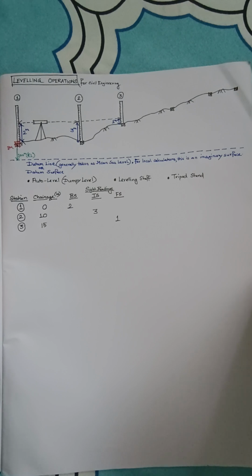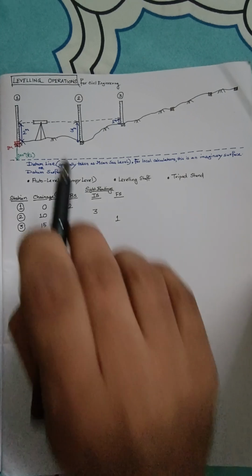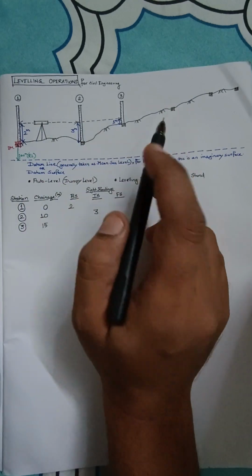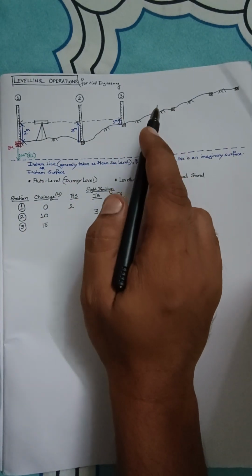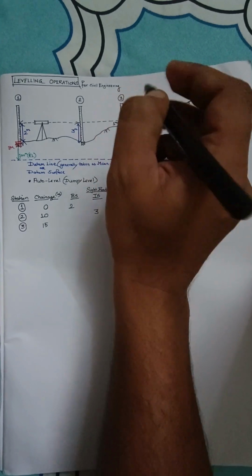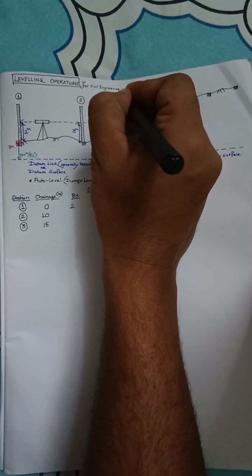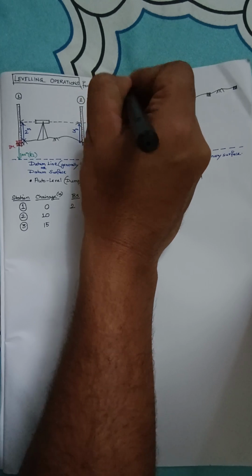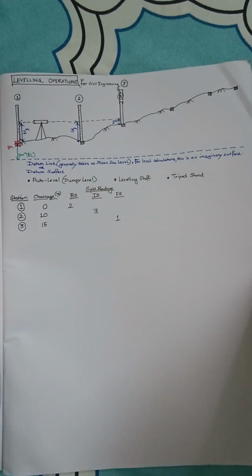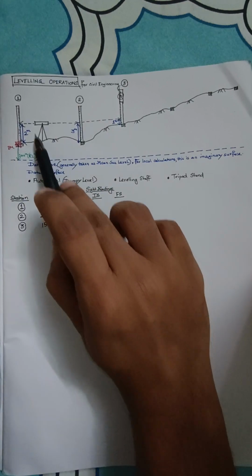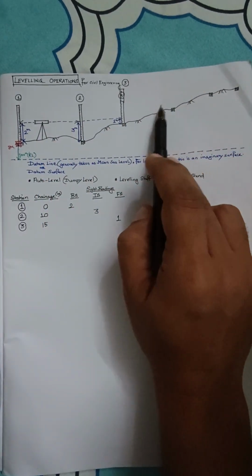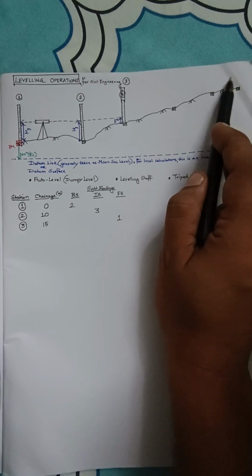Now as I have said already, you actually cannot continue the same setup of readings beyond this. So we have to shift the station, and also we have to extend this a little bit. I've drawn it in a very wrong way. Hopefully you can now understand. I have to write the station number 3 somewhere over here. Apologies for this. Whenever I have to shift the station somewhere over here, anywhere, you can put it anywhere as per your convenience, so that the maximum coverage is attained.